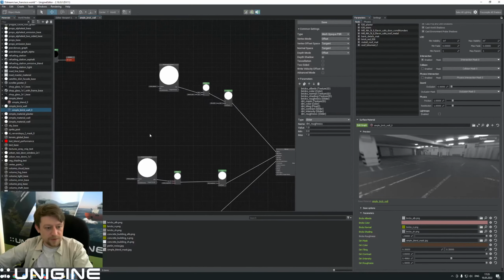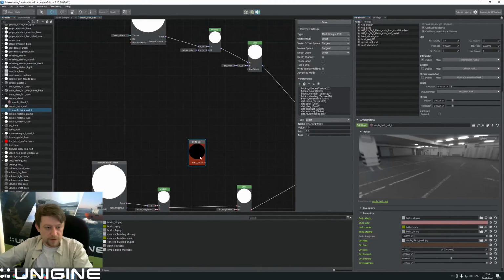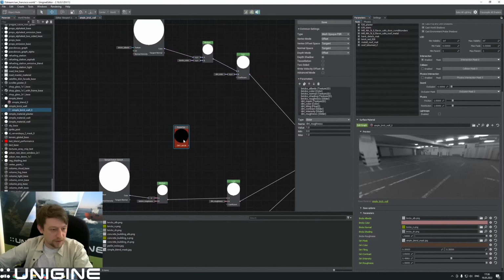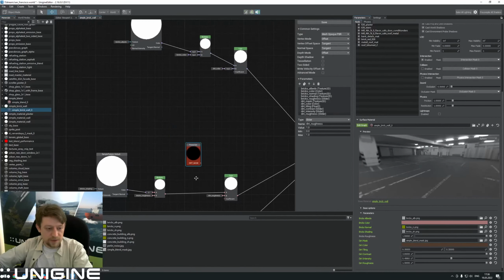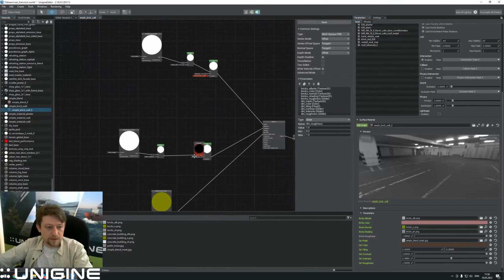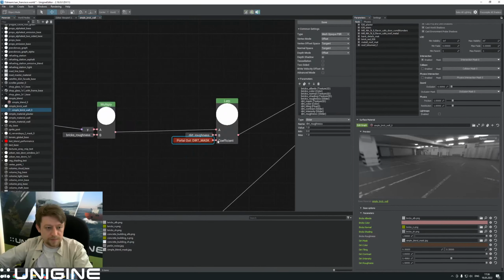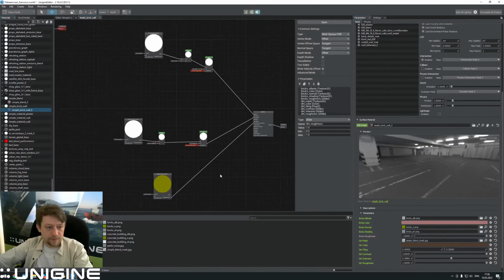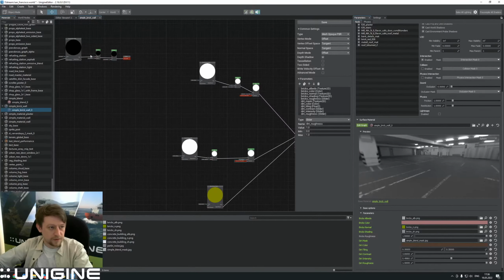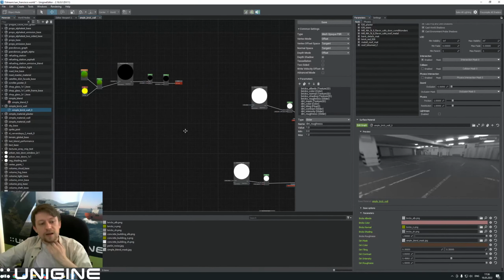And we want to use this mask, so we actually can create portal out node. And if we have a lot of portals, we can just double click on the portal out node and choose the right one. So right now we only have one. We can plug it here, then just duplicate it and plug it here. Okay, save. Nothing changed visually, so let's continue here.